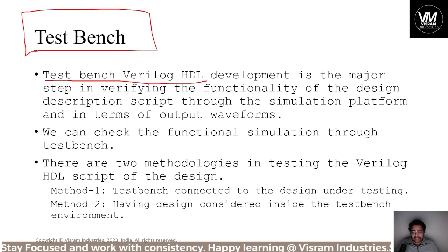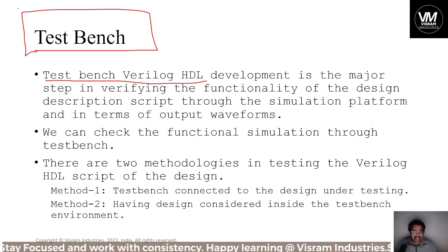For example, we run different types of simulations: functional simulation, behavioral simulation, structural simulation, timing simulation, and we analyze the entire design in terms of timing, performance, or the syntax, or any other internal parameters of the FPGA architecture. So we'll be checking the entire design code, that is again Verilog HDL code. We will test and simulate that Verilog HDL code in an environment that is nothing but a test bench.